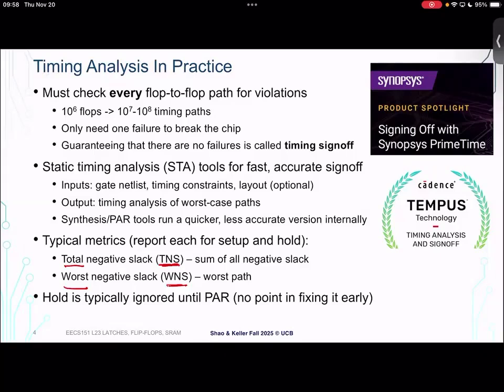So this is getting a little bit into the weeds, but very late in the design process, when the design is mostly done, but there may still be a few bug fixes needed, engineers can do what's called an ECO, which is an engineering change order. You can just think of an ECO as a late fix that's not rerunning the entire synthesis flow, but just making a tweak to one very specific part of a design that's guided by an engineer.